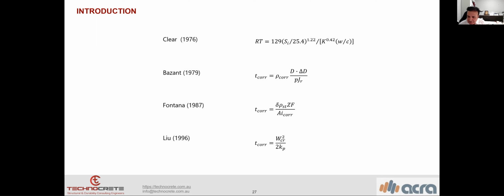But for strengthening, sometimes we need to use carbon fiber rod. For example, sometimes we have a problem in bending, and the carbon fiber wrap or laminate cannot achieve the ratio which we want. Then we have to use carbon fiber rod. Different scenarios have different solutions.